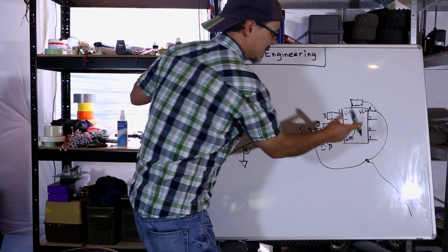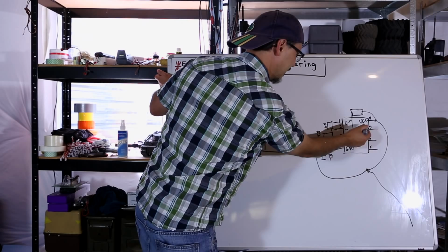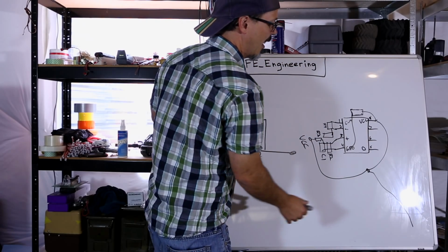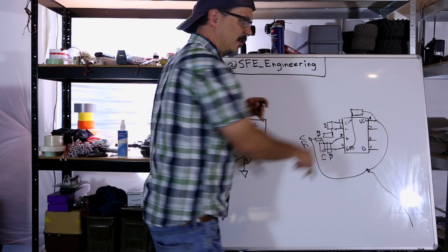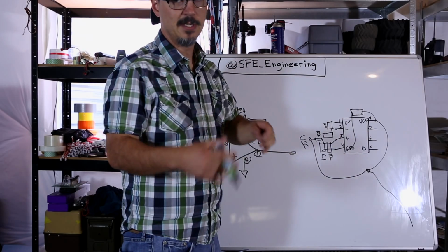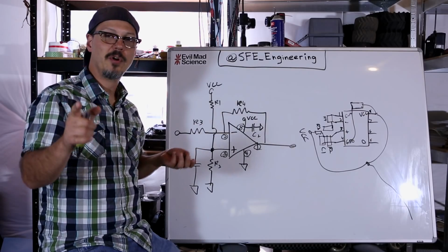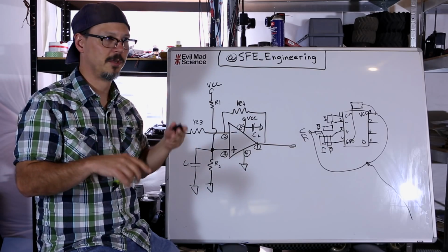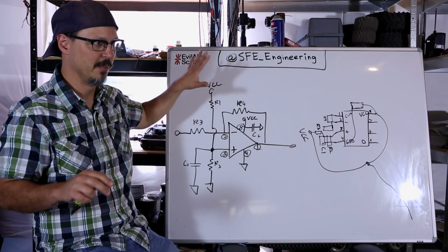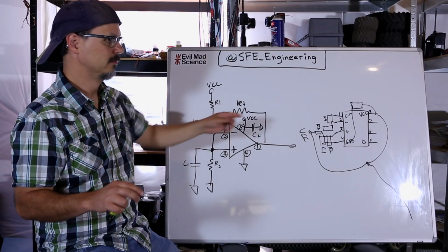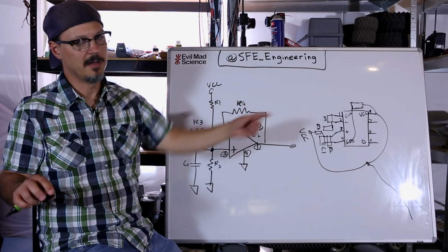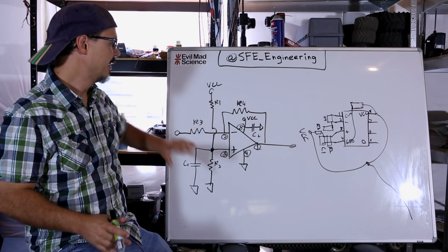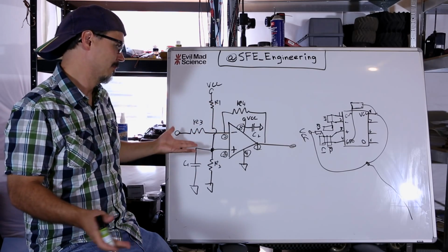You know, there's, let's see, 5, 6, 7. I think the out is here. I can't remember it. I have to look at the data sheet to remember it. But the inputs of this thing, you're going to want to tie either to ground or to VCC, or one to the other. If you put unused op amp into Google, you will come up with a zillion different pictures of how people manage to lock these things down so they don't oscillate. This is just one example, but every circuit section is basically the same by rule.